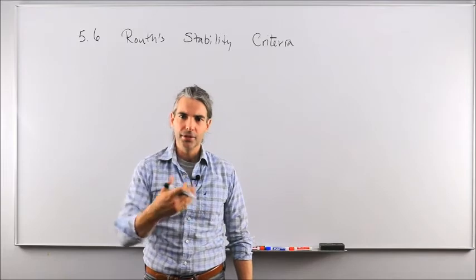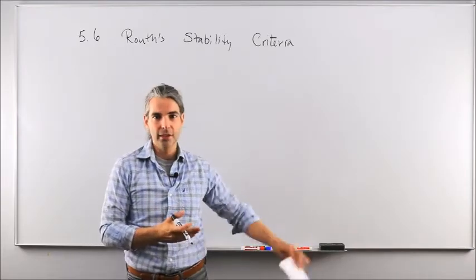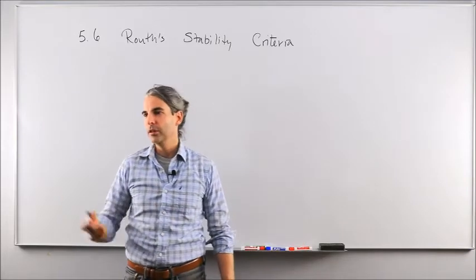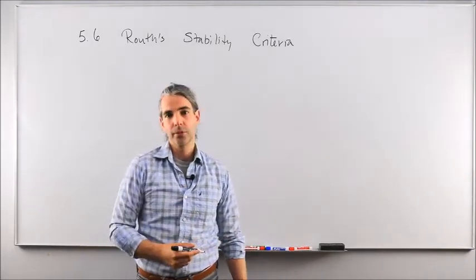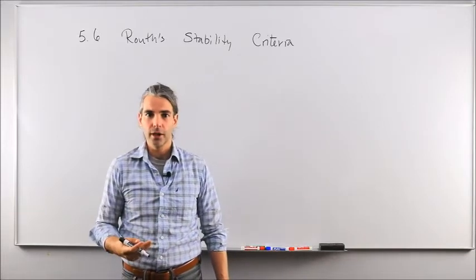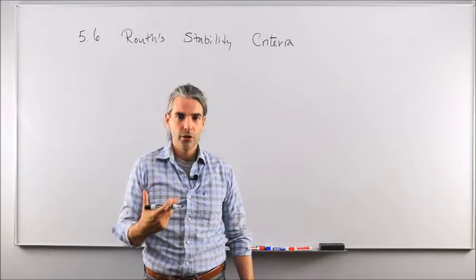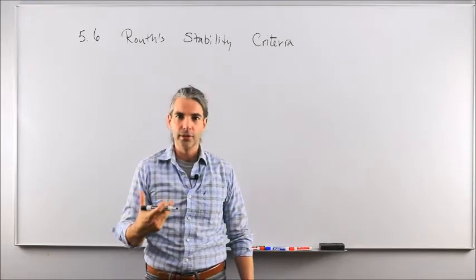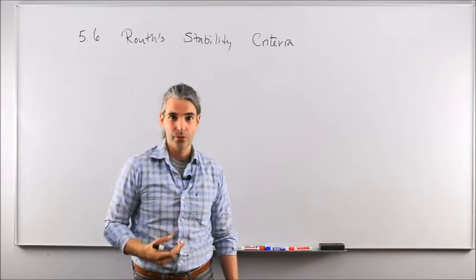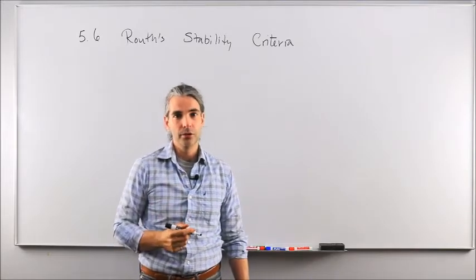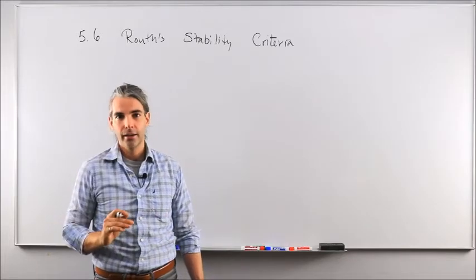But if the characteristic equation, or again, the denominator of a transfer function set equal to 0, happens to be of order 7, well, doing that by hand would be a tremendous amount of work, right? Because you need to extract the roots, or all the terms that would cancel this polynomial, by hand, and you have to solve for 7 roots. Not very easy to do by hand, especially during an exam when the stress level is relatively high.